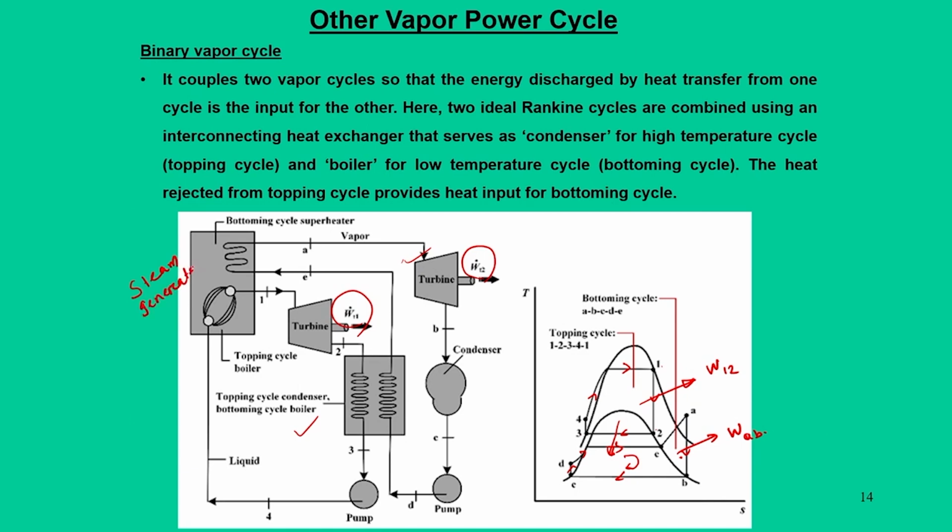and in one case we say it is a conventional fuel based arrangement, the other is a superheater system. That means the steam generation unit consists of a boiler plus a superheater unit, and the superheater unit is for the bottoming cycle, and the conventional cycle works as a topping cycle.